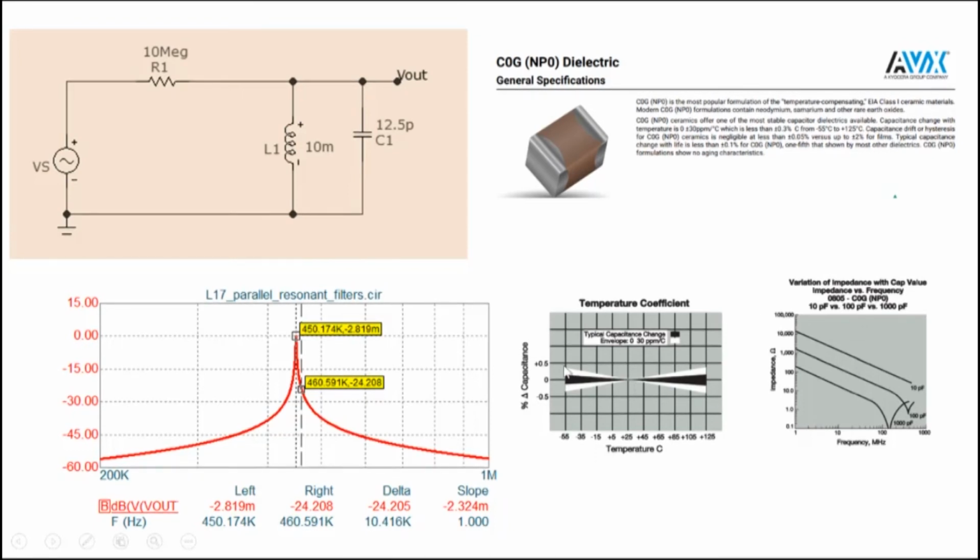But even here, you can see that as you go to higher temperatures or lower temperatures, the change in capacitance is occurring 2-3% at least. And this 2-3% change in capacitance may not be acceptable to you. Okay, this is the other thing that it is showing here, that no matter which component you pick up, it's never perfect. There's nothing called an ideal resistor, ideal capacitor, or an ideal inductor.